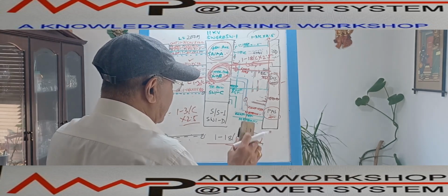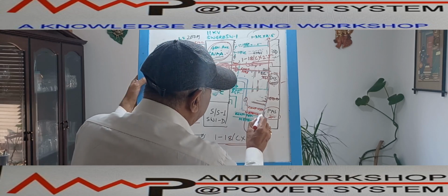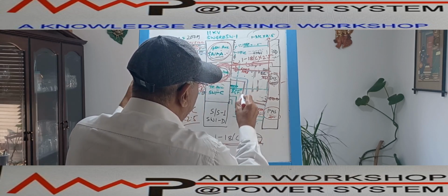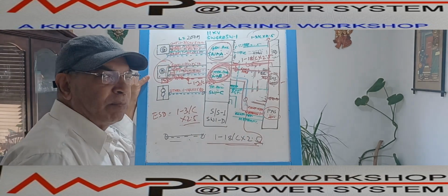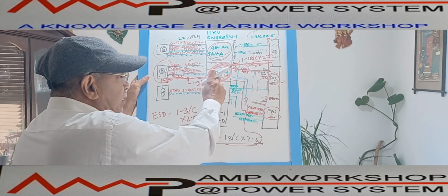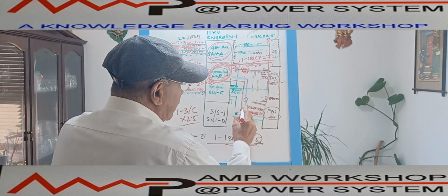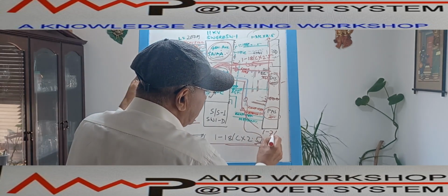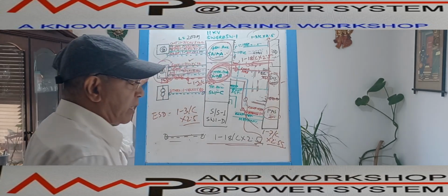Similarly, there is another cable coming from this motor panel, that is the metering cable. This metering cable comes from the motor panel to the PMS panel to monitor the various parameters, current, voltage, electrical parameters. That is also 7-core into 2.5 square millimeter cable, or 1.5 square millimeter cable also we can use.